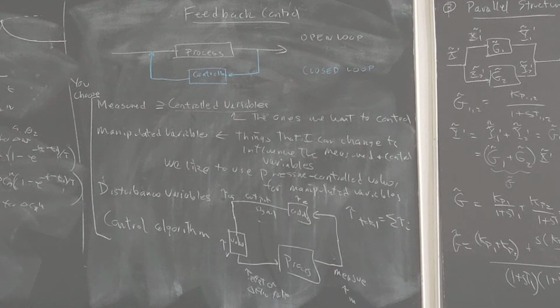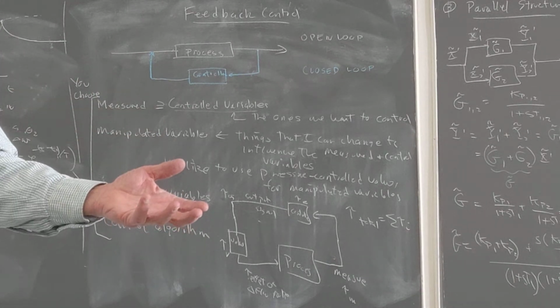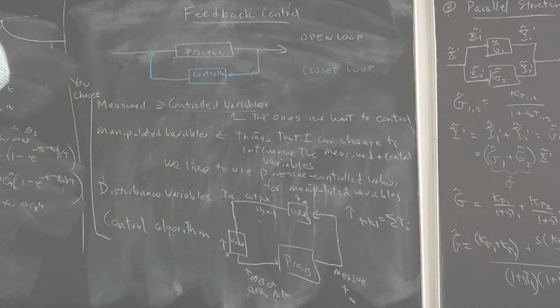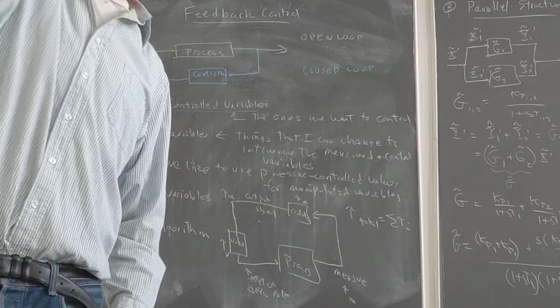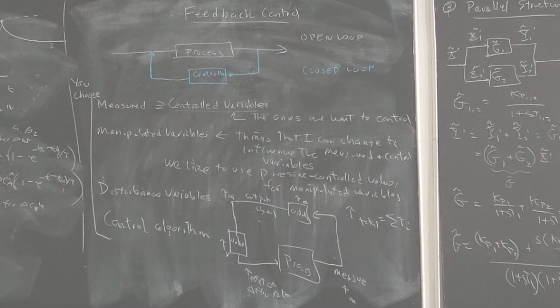And then when it reacts, the water's going to come too hot. So you start turning it down. It's still too hot. If there's a delay, then you end up turning it too much. So notice, in terms of what we've been doing so far, things are oscillating. And they can oscillate and grow and become unstable. So the bigger your time delays, the harder it is to control.